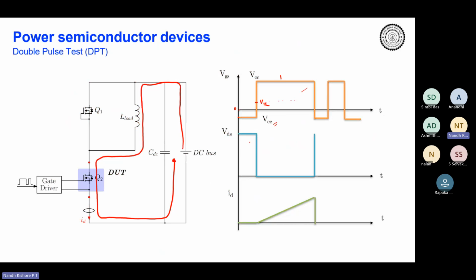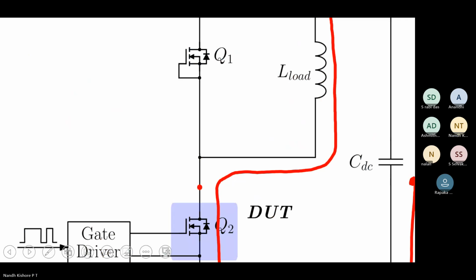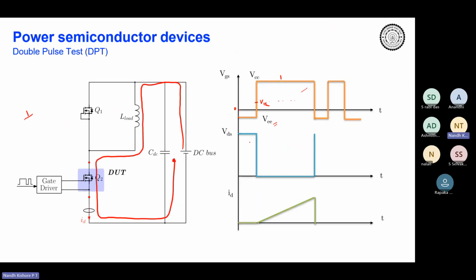So what you are actually having over here, if you draw the equivalent circuit, is a DC source and then an inductor, and that's it. You don't have anything else, correct? The switch is on, so you have a constant DC and try to flow a current through the circuit. The current would increase linearly because V is equal to L di over dt, right?